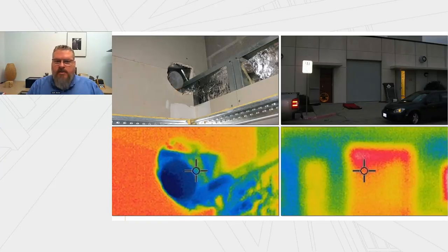I'm here with a temperature differential. This was a cold weather evening, so you've got cold air outside. You need at least a 10-degree Fahrenheit difference between the interior and the exterior typically. And then we'd like to do this with about a 25 Pascal difference. Different people have preferences for different pressures and what they're used to seeing. And you're looking for the effect of air leaking, in this case, we're pressurizing the building.